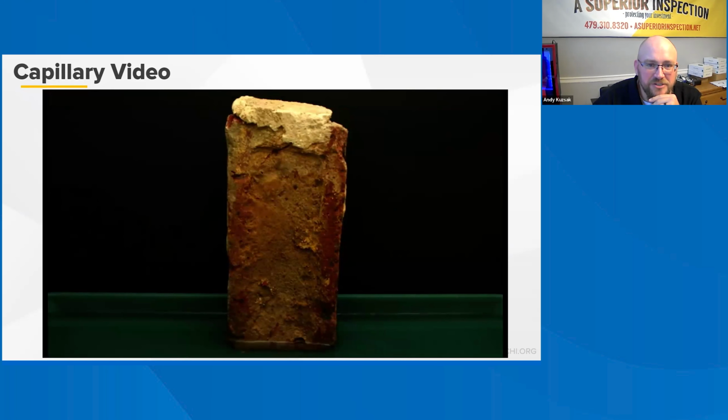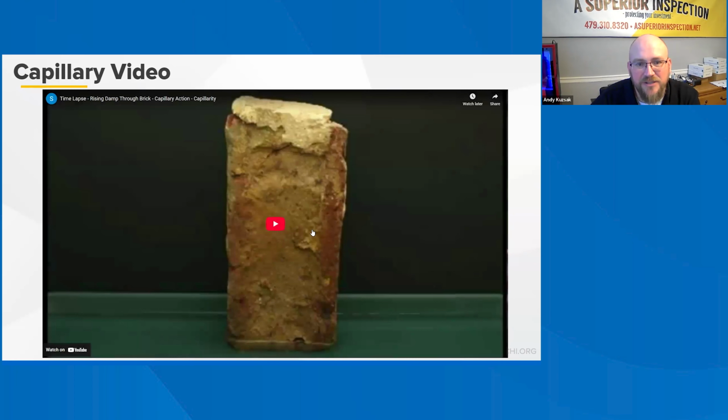So bricks are like sponges. And so if you have a house with no gutters and you have a brick siding or brick cladding, negative grading, all that water is falling back next to the foundation and is soaking back up the exterior brick cladding.